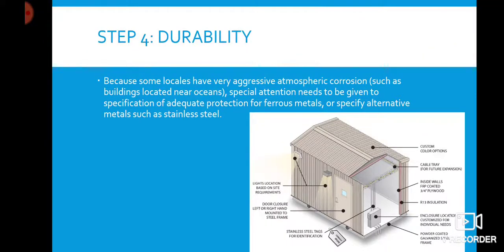In some locales, termites present a significant threat to building performance. Where termites are problematic, it is recommended that the soil is treated with a termiticide applied by a professional company experienced in termite treatment. It is also recommended that if wood or wood-based products are specified, they should be preservative treated. Also specify that surfaces that are cut or drilled after treatment are to be field protected with a suitable preservative applied in accordance with the manufacturer's recommendations.